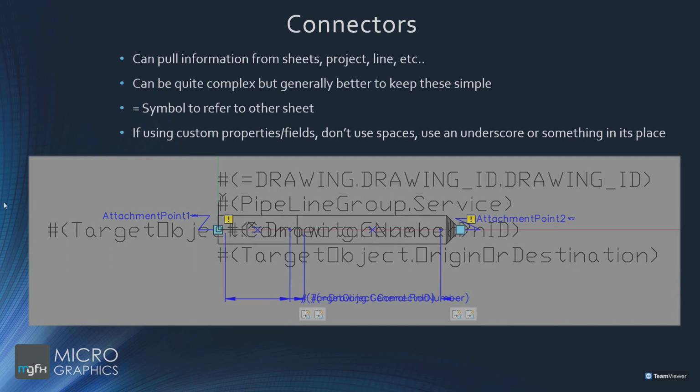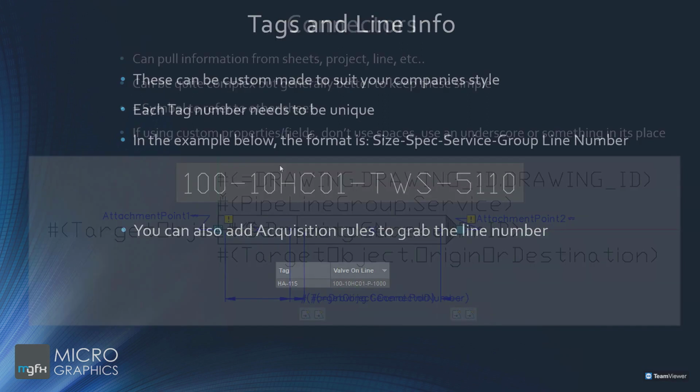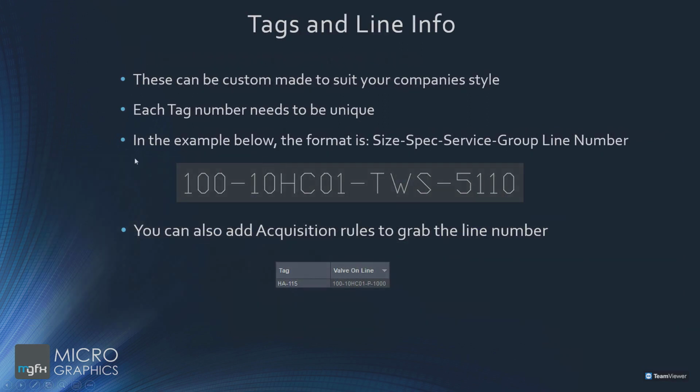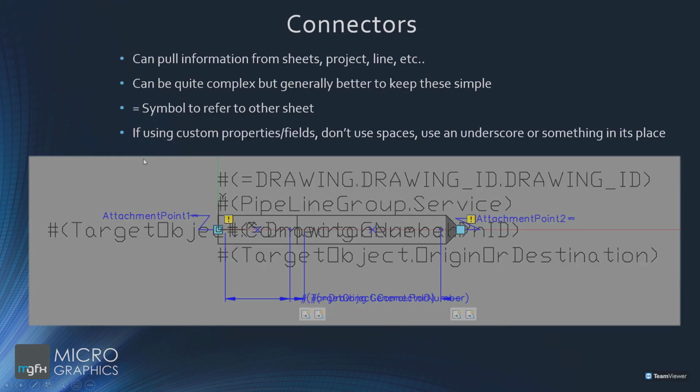If we're taking a look at something like our connectors, and you take a look at the bottom, I've purposely shown you guys the default connector because it can show you how complex these things can begin. And this is, like I said, a bit of an exception to the rule about dynamic blocks, but I honestly wouldn't suggest going into this level of detail because it confuses me sometimes, so not such a great thing. You can have a lot of information in things like your connectors, etc.